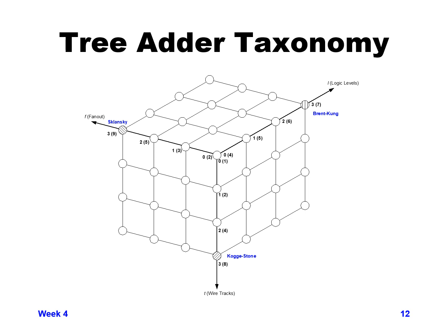A fan out of 2 is the largest, but you get 7 logic levels. Now, the other two designs that we previously looked at, the Kogge-Stone is basically as if you had logic levels small l of 0, small f of 0, but T of 3. So here you see for a 16-bit adder, you'll need 8 wire tracks, but you'll only need a fan out of 2 and logic levels of 4.